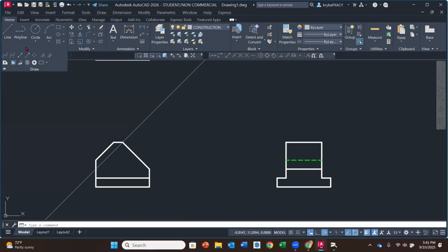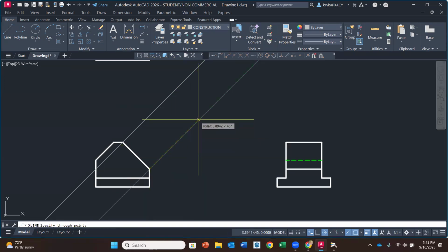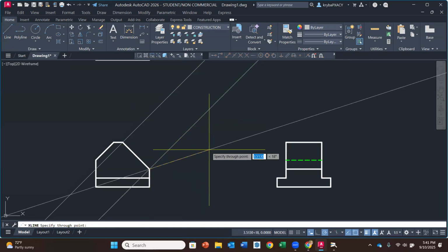We're going to do the same thing on our other angle or our other edge, which is down here. So I'm going to left click there, kind of go to that 45-degree angle, and then left click again, and then escape to end that. I'm only focusing on this area. And the reason I am, otherwise I'd be putting up all the other lines and it's just a lot to look at. So I want to focus on that surface and the hole to start.